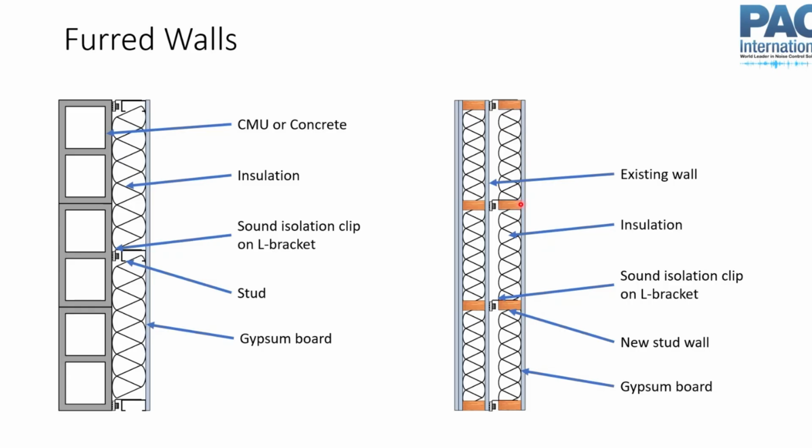Too, you want to make sure that this is all sealed up, and having this kind of double wall situation can be helpful, because if there are penetrations in this wall, now if it's a fire rated wall, hopefully there's not a bunch of penetrations in it. But if there are, and maybe you can't seal them, you can't get to the back side, the other side of this is another tenant, you can't control this space, you just don't know what's going on over there, you can use your side plus this new wall to make sure you've sealed up and addressed the cavity path too.